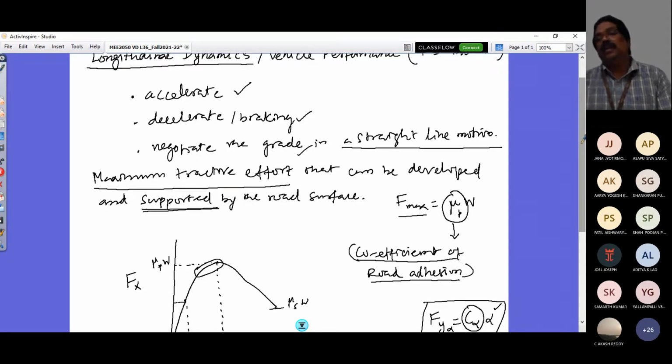So you have an expression for the driving torque applied, and from that the corresponding tractive force would be obtained. How? You divide that by your tire radius, and then divide by the mechanical efficiency of transmission and so on, and then account for some mass loading effect, and you would have some tractive force.